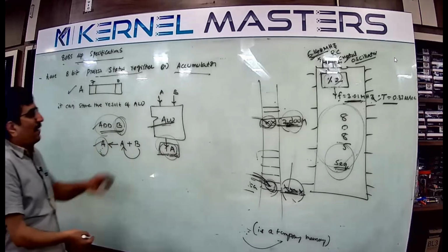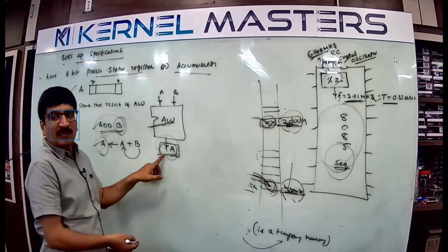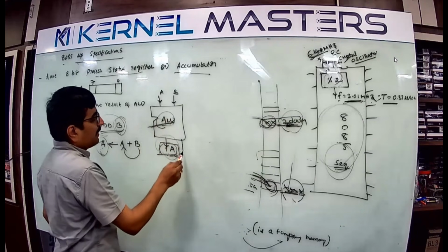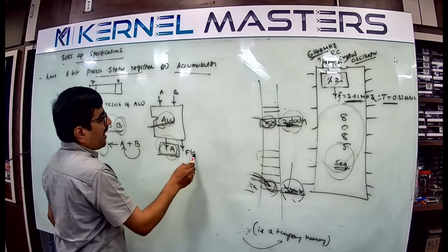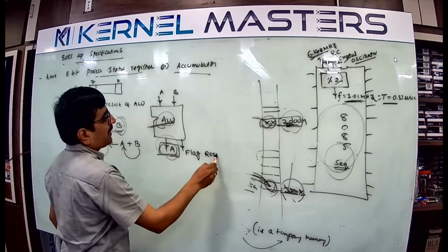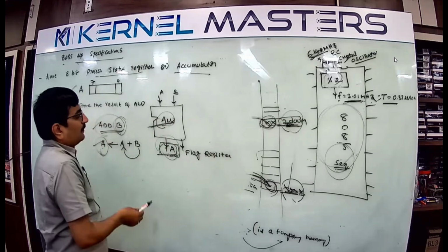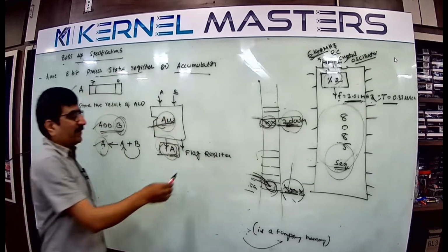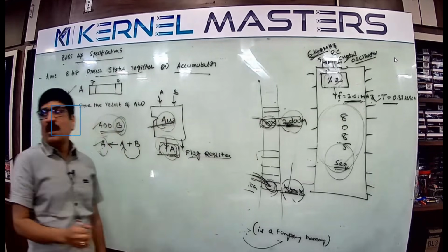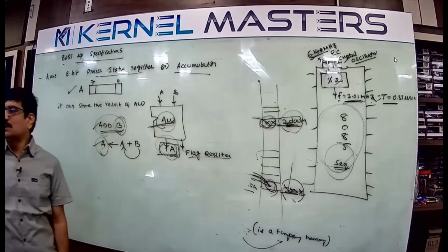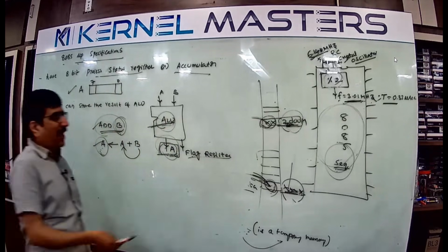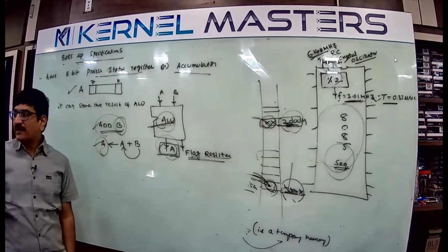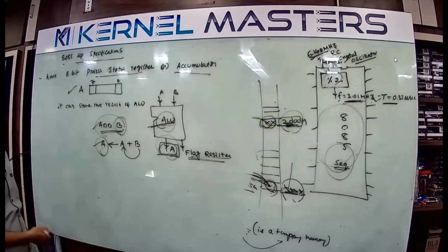After an ALU operation, you can check the result in the accumulator, and one more result also comes, which is called the flag register. It's a very important register. Once an ALU operation is performed, depending on the result, flags are affected: carry flag, zero flag, sign flag. The flags indicate whether the result is zero or non-zero, which is useful for comparison.